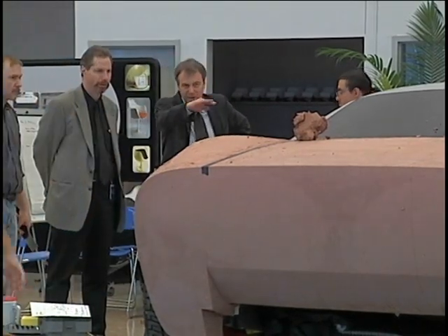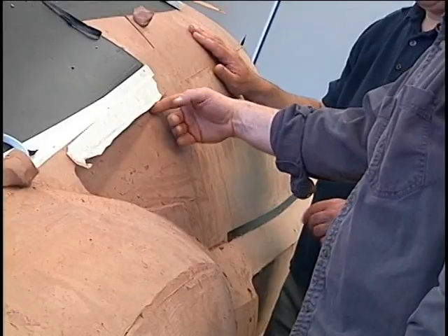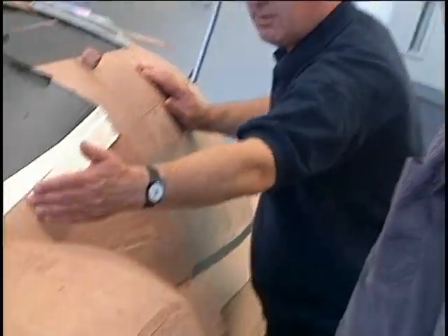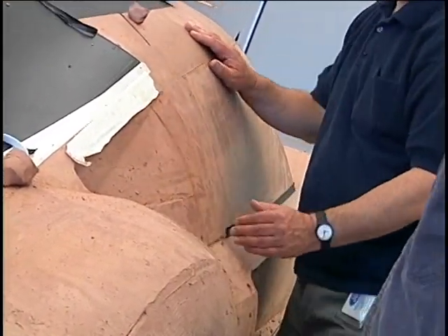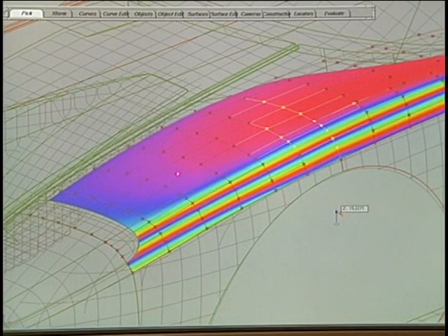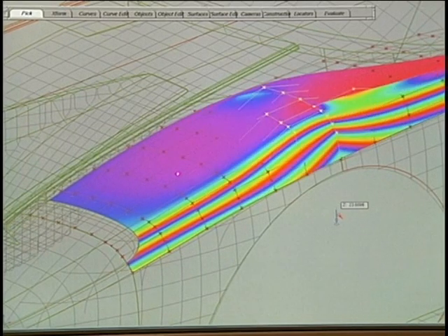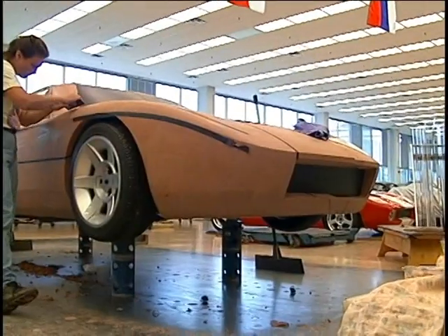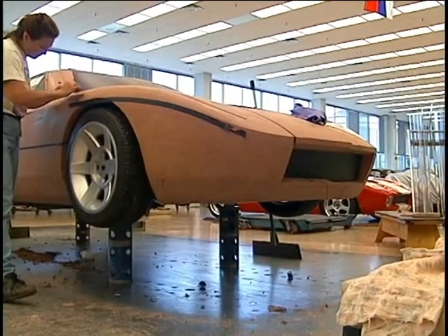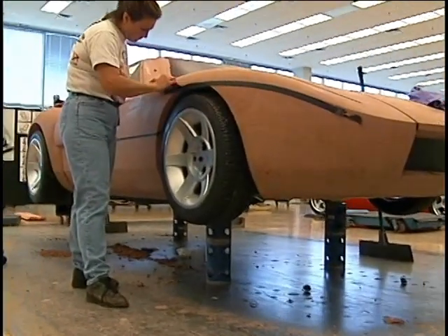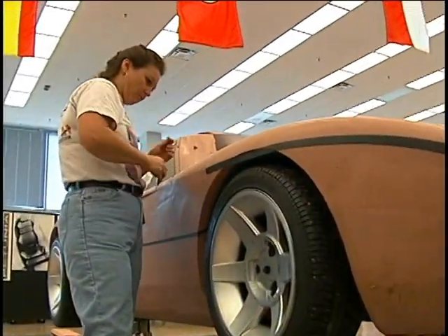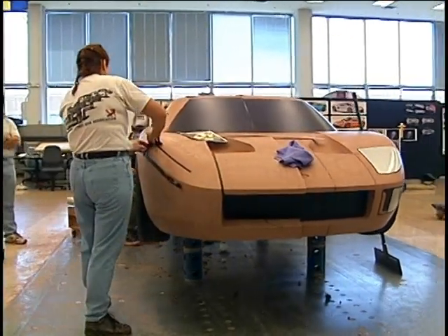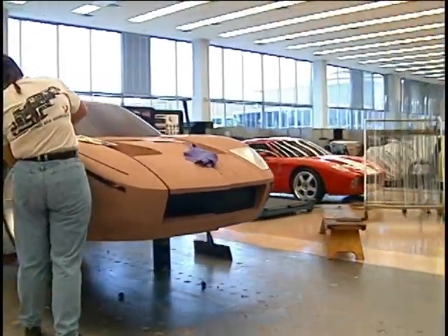Design management decides which areas need to be readdressed. Proportions, stance, front view, rear view, and side profiles are all evaluated together to understand the designer's intent. The design can be further developed using the Alias software in the computer, or the team can elect to make changes by hand, with the modeler sculpting the clay to fine-tune the surfaces before being scanned back into the computer. This scanned information can be used to duplicate the model from one side to the other and to continue the design development.